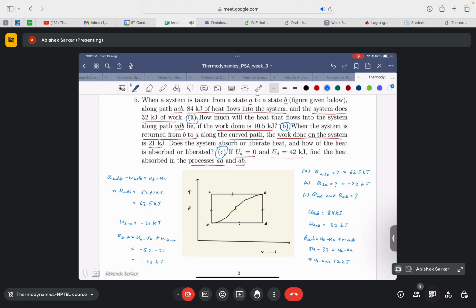Check whether it's a constant pressure process or a constant volume process. Processes, by here I would mean separate processes. Is process AD a constant pressure process? Is process DB a constant volume process? What happens to the PdV work when it is a constant volume process? Use that concept, you will be able to solve it.